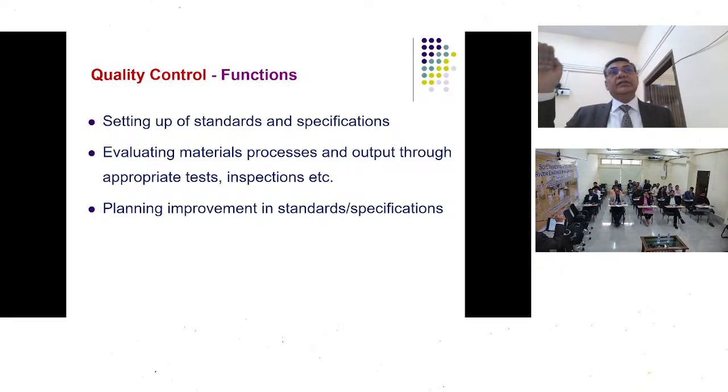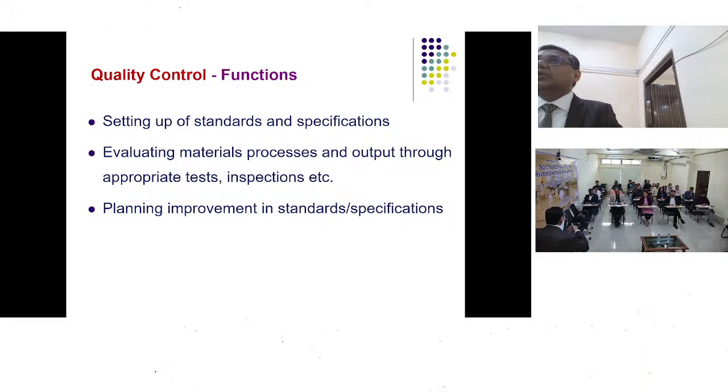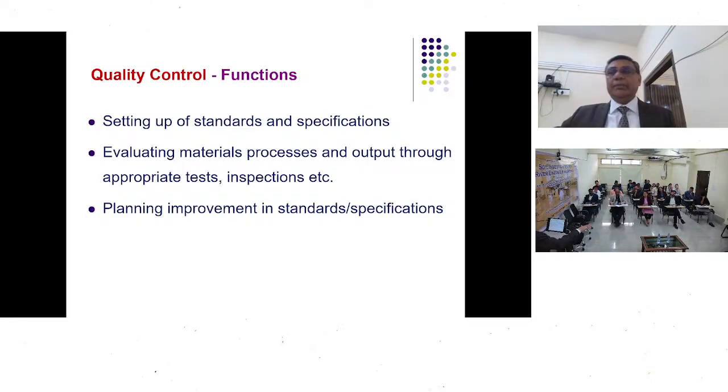Usually what happens in the wake of the progress, you'll say 30 centimeter or 35 centimeter or 40 centimeter, everything is okay. But as a QA personnel, you need to have that critical eye of seeing, no, this is not 30 centimeter. You have to stop it and get it corrected.